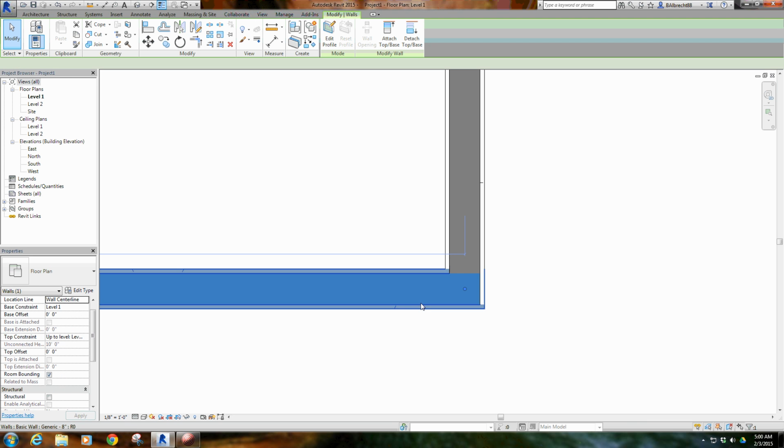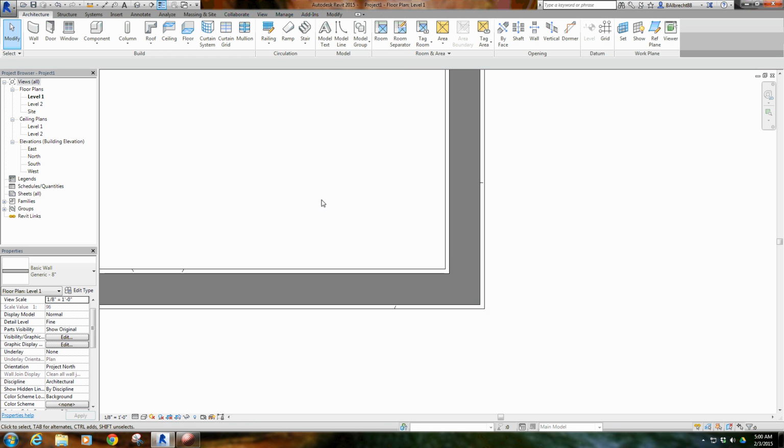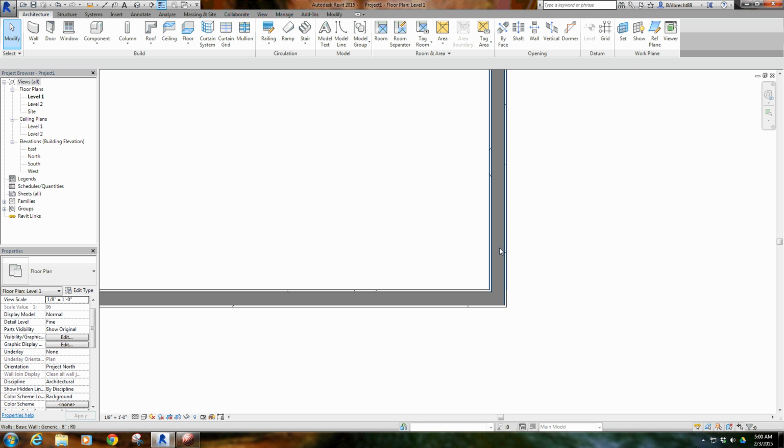So that's something that as you create more and more layers, you can specify which ones wrap and which ones don't. So maybe on the ends, if you had your substrate, your airspace, and then your stone or something like that, and for whatever reason when you returned you didn't want the air gap, you just wanted the stone, you could click the air gap wrapping off and it would just take the stone there. So in terms of creating walls, that's pretty easy.